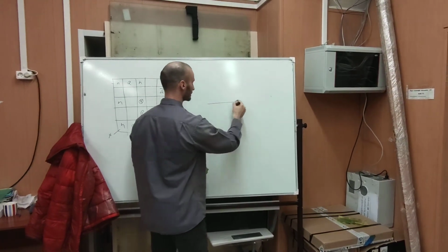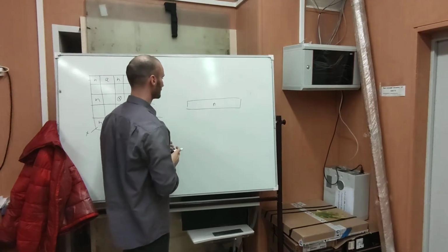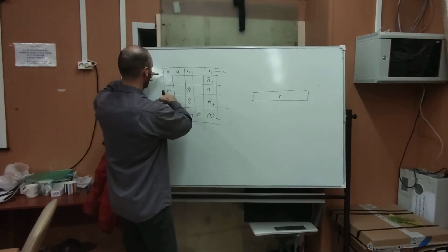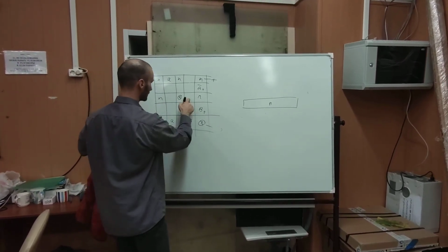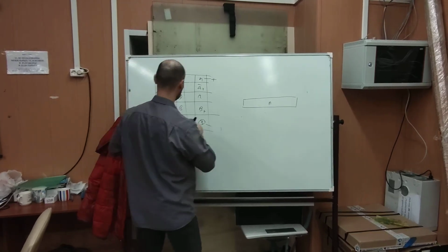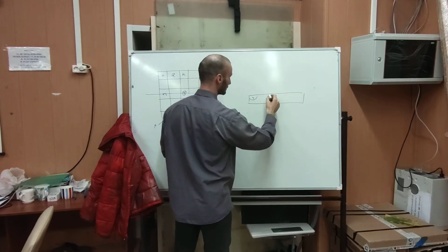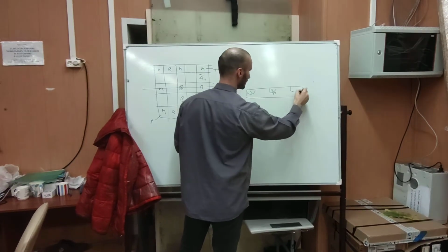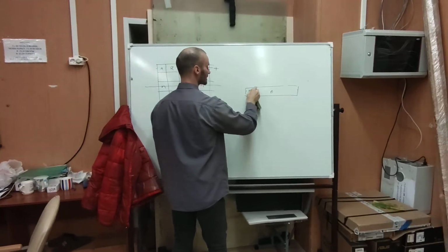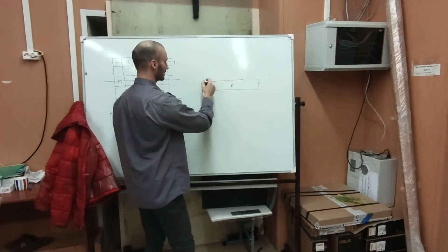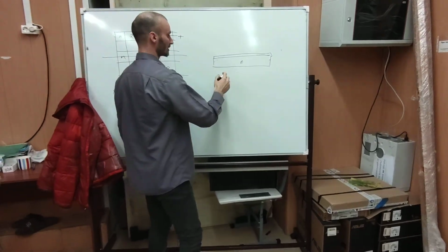So we have silicon wafer, a lightly doped p-type silicon wafer, and we need to make this grid of n dopings. So here, here, here, here, here, here, and here, here, here. And that's a cut like here, for example. So we need to have n dopings here. So what we will do is first we will spin coat this substrate with photoresist, and we will apply